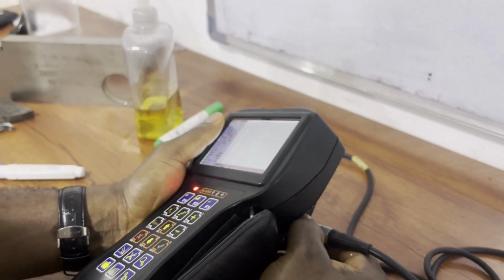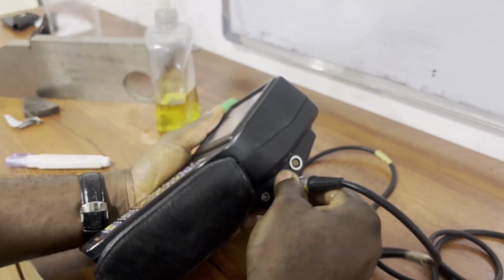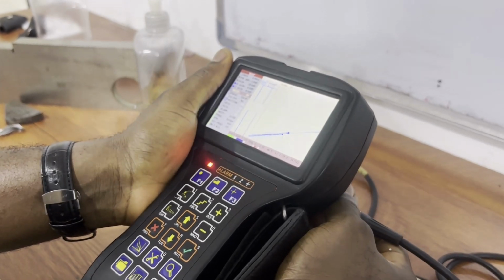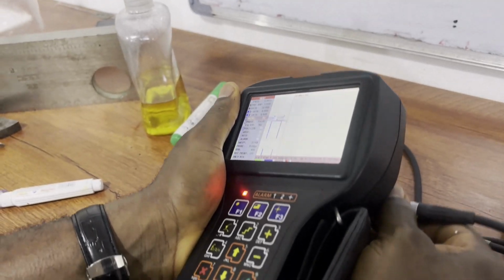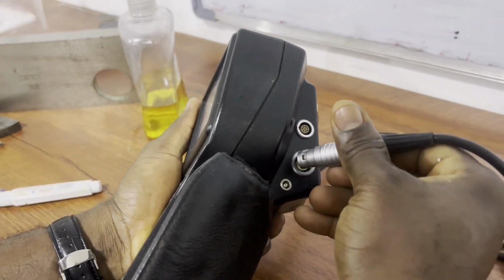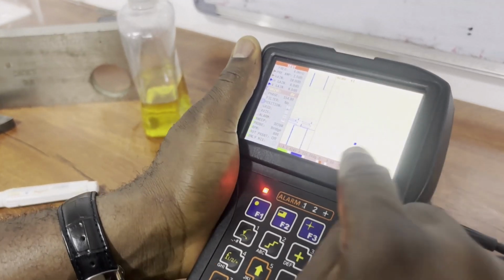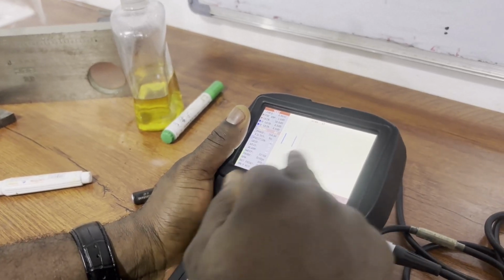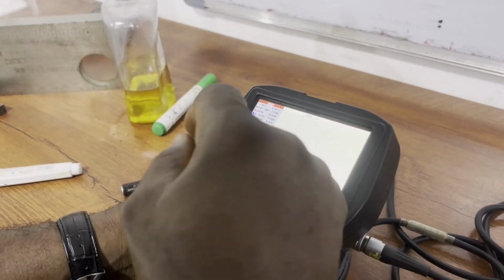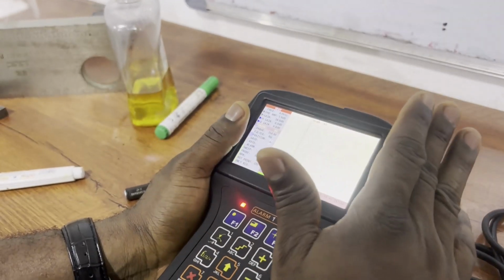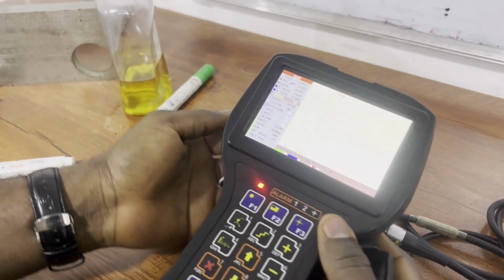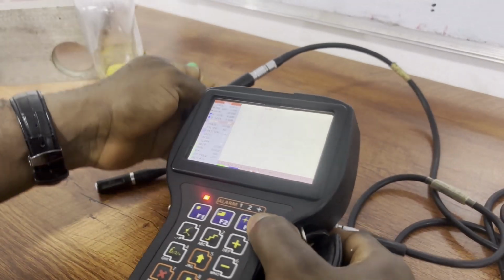Now, this is the part where you will know if the probe is working. So I disconnect. To know if the probe is working, look at your screen. Immediately you put it, your screen should show some change. You see? It shows you that the probe is working, because by me connecting the probe, you have seen changes in your unit. I tried it a third time, you see? If you put the probe on a unit and you don't get any signal, any glitch, just know that that probe is faulty. It's as simple as that. There is no other test for that apart from going to the lab. But if you put it in your unit, it should respond.